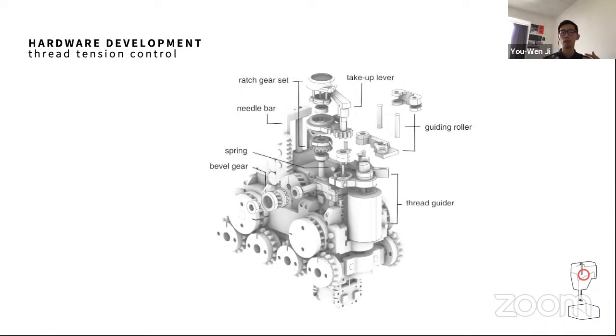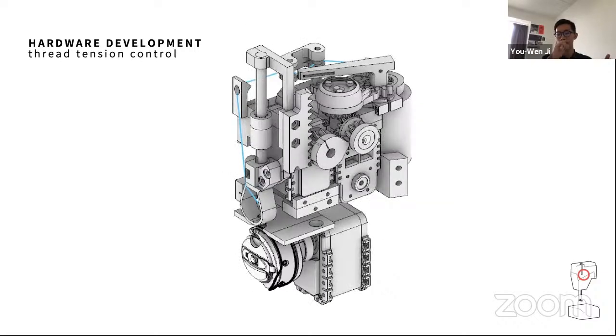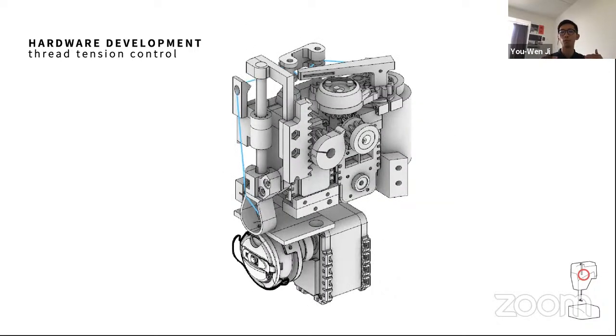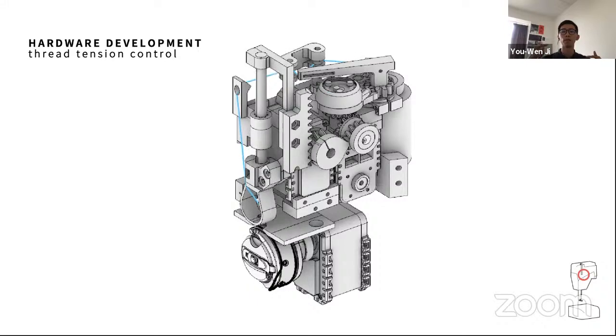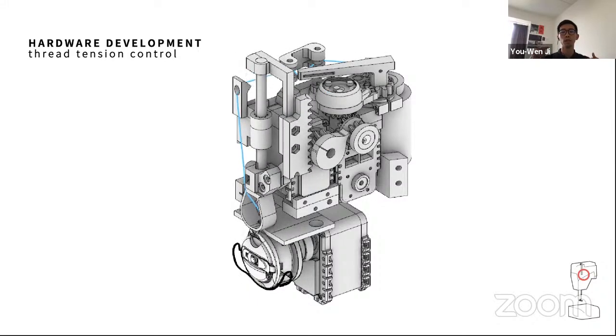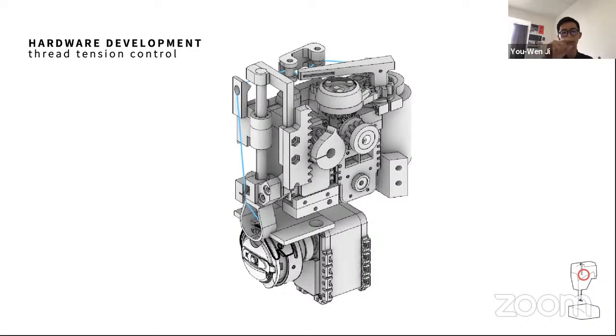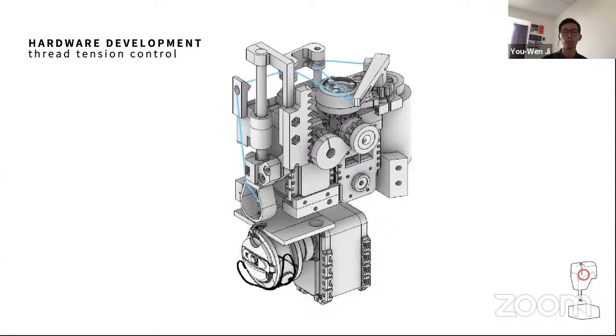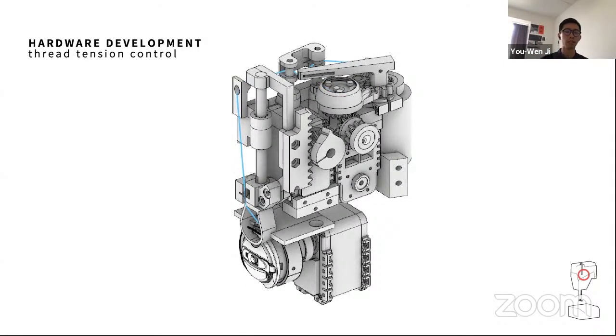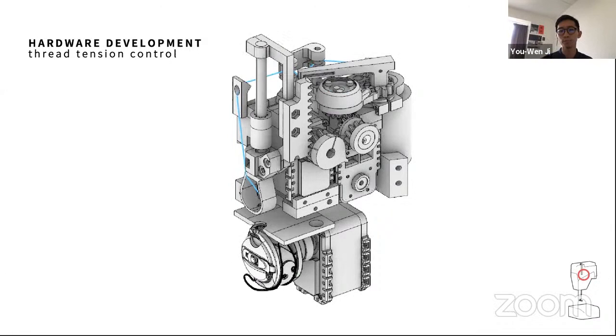The stitch bar has a customized lever arm to minimize the size. The lever arm will pull in the thread while the needle is leaving the fabric to the highest point. Then the lever is made of 5 pieces, which you can see from here. The horizontal lever arm will be moving. So that's the only reason we use a really complex gear set to design this.